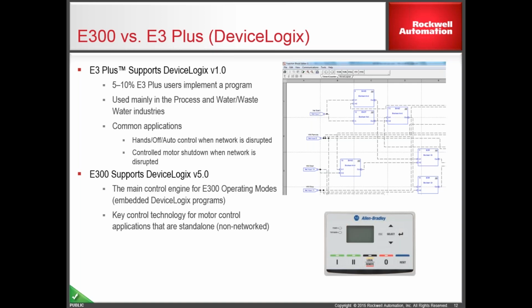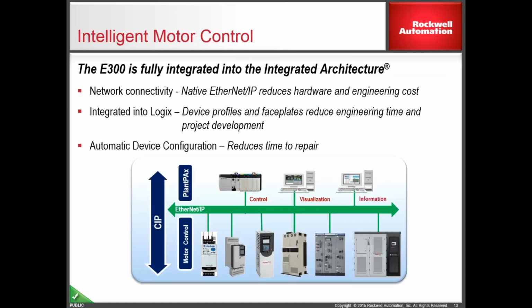Also with DeviceLogix, one thing I did want to touch on is that a lot of times we see people using it as a backup control. So if at some point you ever lost communication with your PLC, you could use the DeviceLogix to keep your process running, or you could also use it to gracefully shut down your process. So you could just keep the logic running as it is, or put something custom in there to try to shut down.